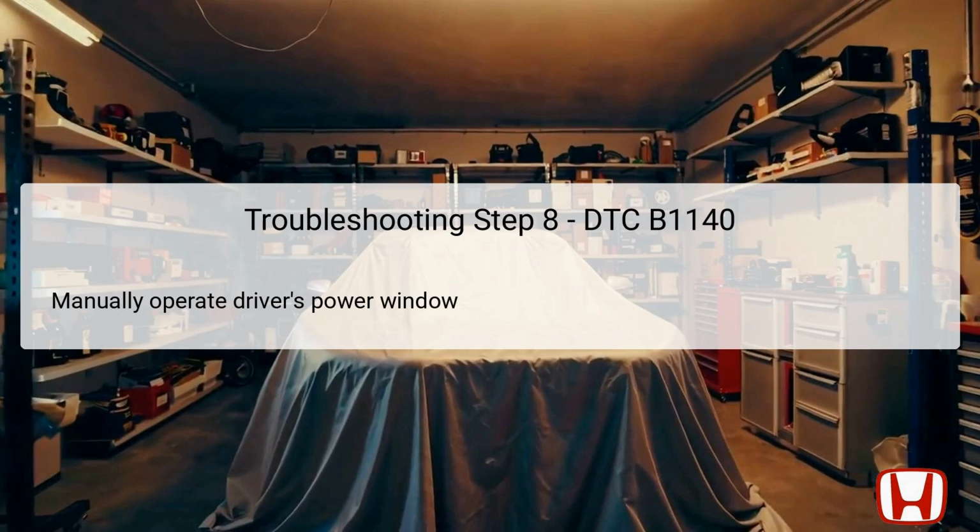Conversely, if the window still does not respond appropriately, it suggests that the problem lies elsewhere, possibly with the power window motor or another component in the circuit. This stage is about confirming the success or failure of your previous troubleshooting step. Always ensure to collect diagnostic data during this testing for a thorough review later.